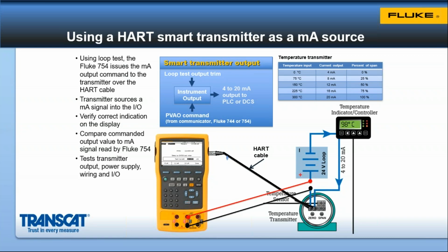Very useful. Actually quite similar to doing the transmitter substitution test, but in this case, the transmitter is remaining inside the circuit and you're using the output of the smart transmitter. So it's really a very powerful test in determining the integrity of the control loop.